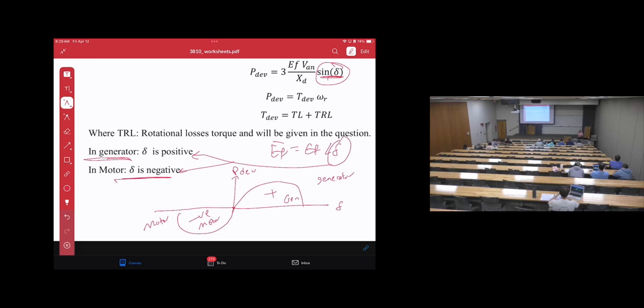So this nice feature allows us to use it sometimes in EVs or even in some electric scooters, by calling regenerative braking mode. Basically, when you press the brake in an EV or a normal vehicle, it will go to the normal brakes, like there's a disc, then brushes. This is a mechanical brake, and this will go as losses. This will impact the brushes, so maybe frequently you need to change the brakes, right? And all of this will go as losses, because let's assume that you're driving down the hill and you're pressing brakes.